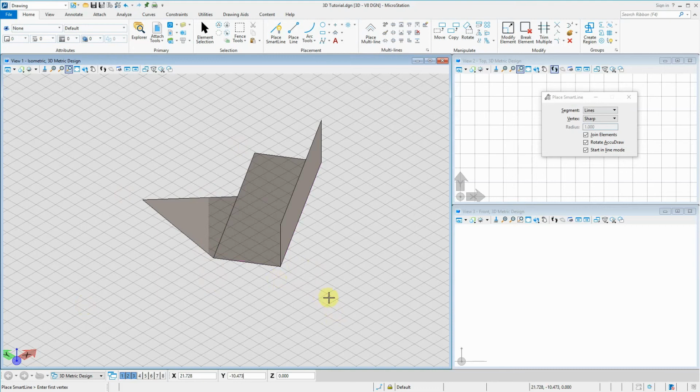Now, there's a couple of other things with Accudraw as well. If we press on the shape here, and we press T for now, and then we press the letter M, you can see how it changes. So this is more towards, you see down here, distance and angle. So if you want to draw an angle, or to a certain degree, an angle to where the origin point is, this is how you would do it. You press M, and then it allows you to input those parameters in there. Otherwise, you go back to the X and Y. So it's M for shortcut.